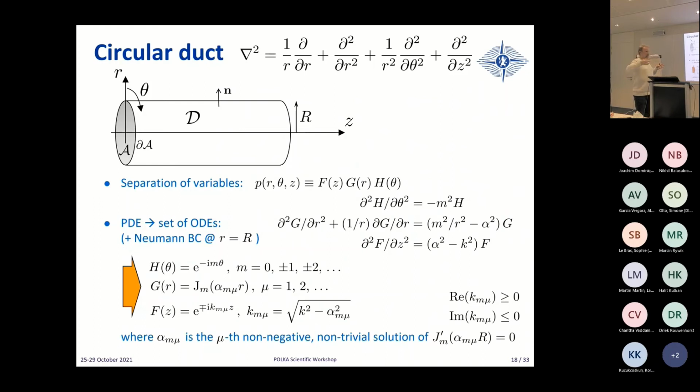So you can have an evanescent wave that still propagates, so to speak, over a certain distance before it decreases. So you have to be cautious when you are playing around, I mean, if you're really close to the cutoff frequencies. Yes, you go from a propagating mode to an evanescent mode, but locally it can be slowly decaying.